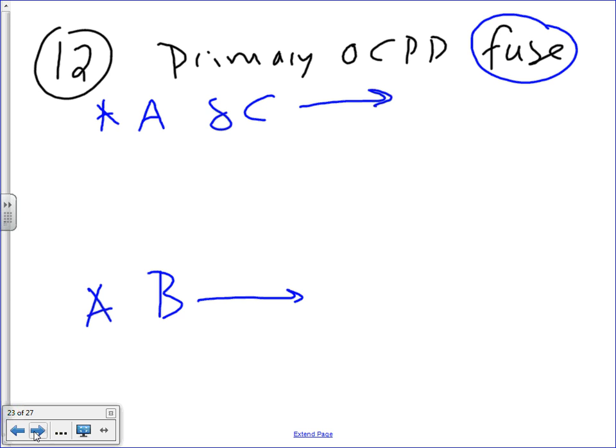For fuses, I will remind you, guys, we go to table 450.3, A or B? A. Why A? Thank you. Higher than 600 volt. Okay, so let's take the first A and B on the primary. First of all, there was 94 amps.